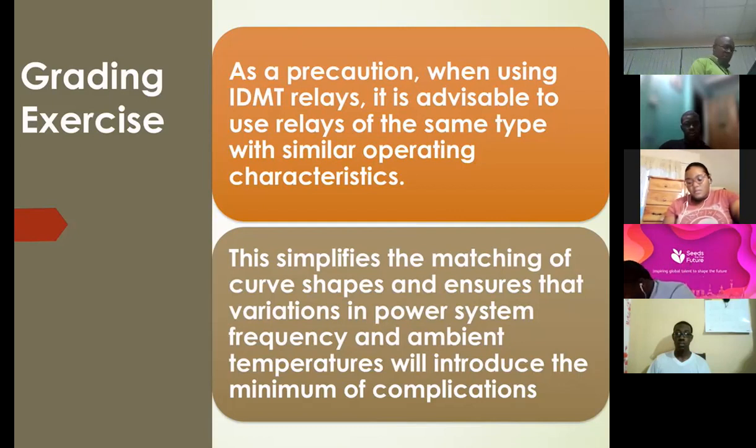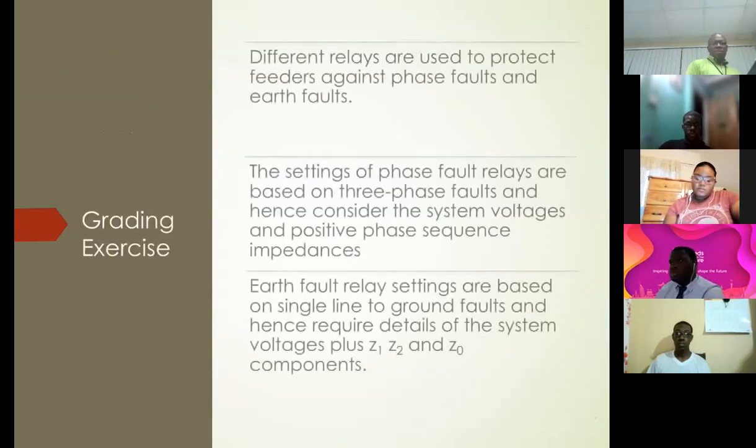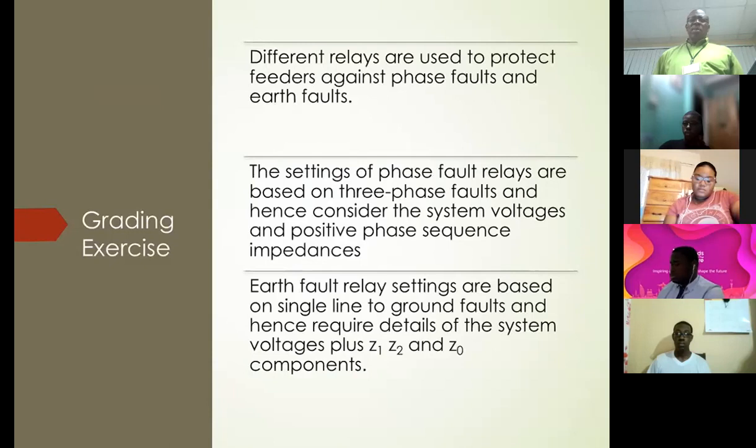Another point I want to make before we jump into the exercise. In terms of the relays, you're not going to use the same relay to protect against phase fault as against earth fault, because of course the settings are going to be different.